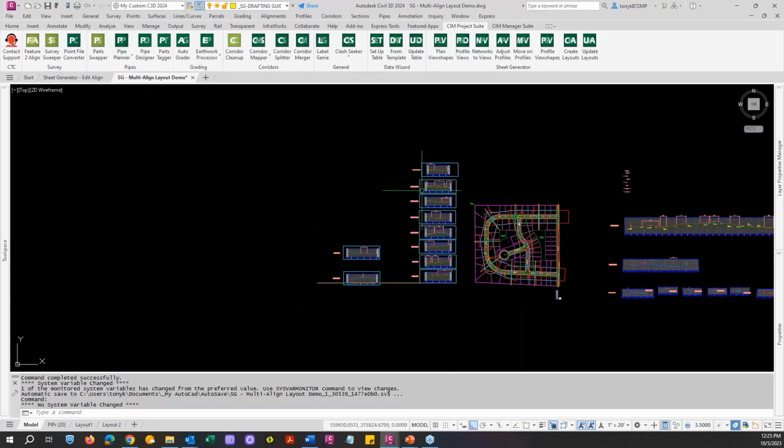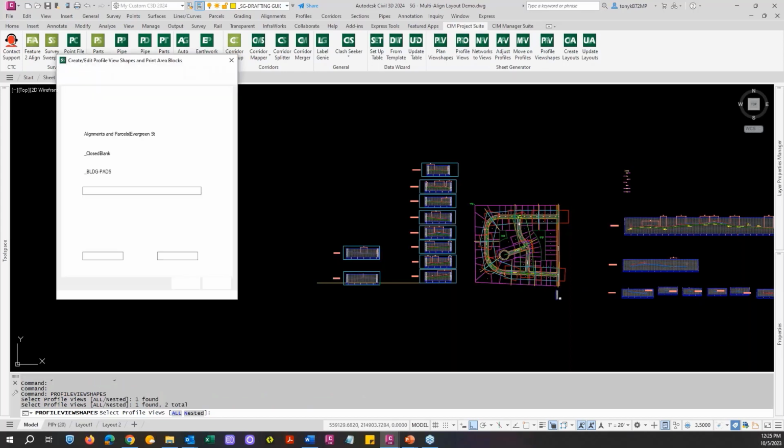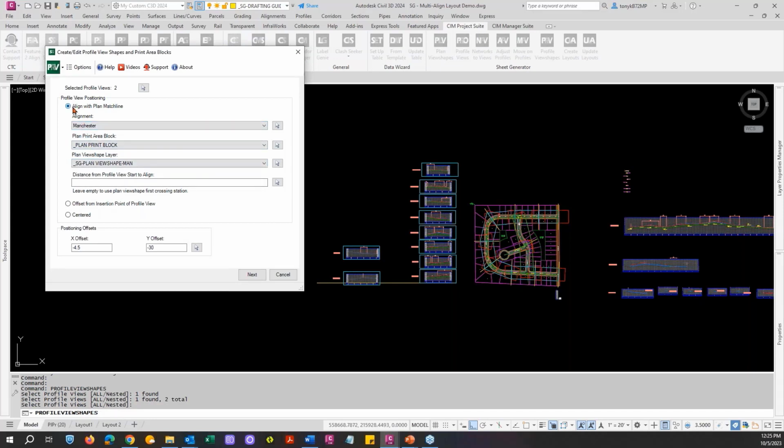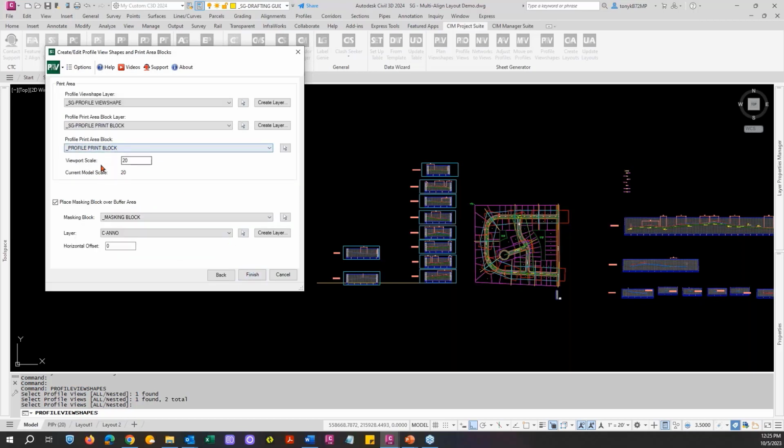And we left it to do the same match lines. I should have shown you that. Let's just go back to that real quick here. So we have this selected again. And like I said, this held, so it's always going to be the same. And it probably will be for you too, whatever scale you're using. So this is going to scale it to the 20 scale. If you had it 30, 40, 50, whatever you had it, everything will be adjusted within there.